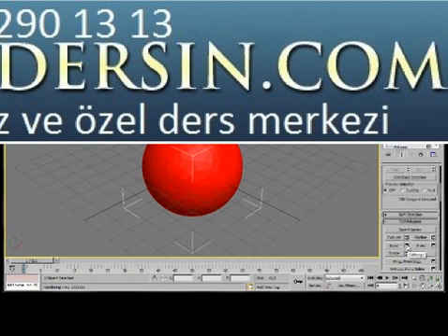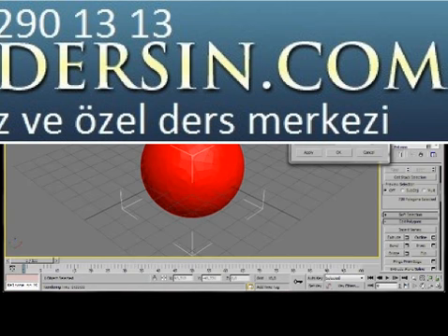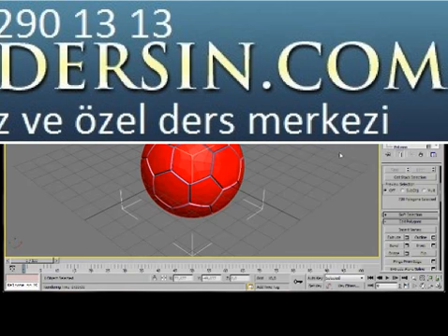Select the small settings box next to the word bevel. Under bevel type, choose local normal. Under height, we're going to insert 0.8. Under outline amount, we're going to insert minus 0.5. Then OK. Just one more thing to do, then we can start assigning some materials.